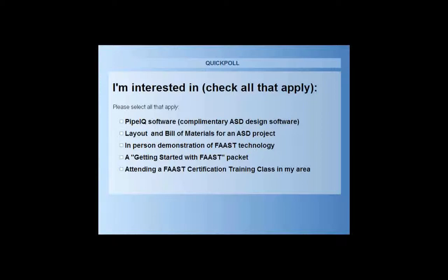Typically, the answer, without looking at it, is no. These certain items would affect, obviously, beam detection operation in these areas. Again, we say banners. If it's a banner that's the size of, acting as a wall, then we have to take wall considerations into play, and keep treating them as separate environments. But if it's banners, balloons, and things like that of nature, no, they will not affect the piping network and the level of detection provided by air sampling.